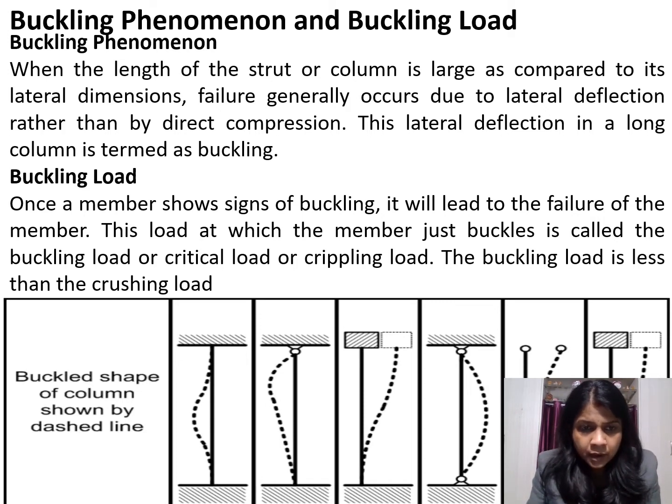At the end, as the column is rigidly restrained by the support, bending has not occurred up to some distance, and after that the column has been bent, and the maximum bending has occurred at the center.